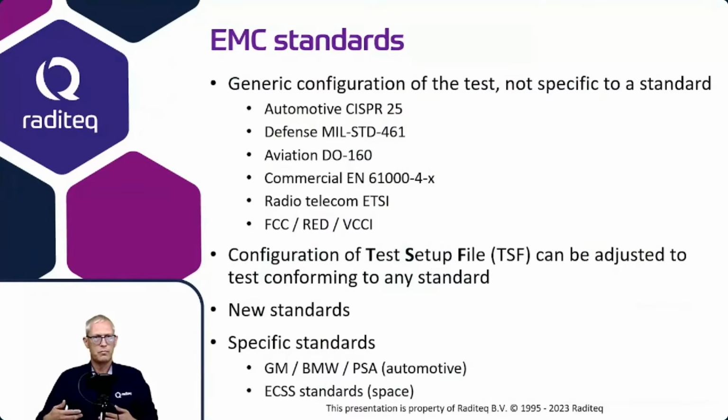And then we also support different standards. However, there is no fixed standard known in RadiMation, because we have a generic configuration of the test, which is not standard specific. And we have a test setup file, which is the configuration of the test. The test setup file can be configured to use a start and a stop frequency and a test level and a modulation type and so on. And all the important settings are available to be configured in the test setup file.